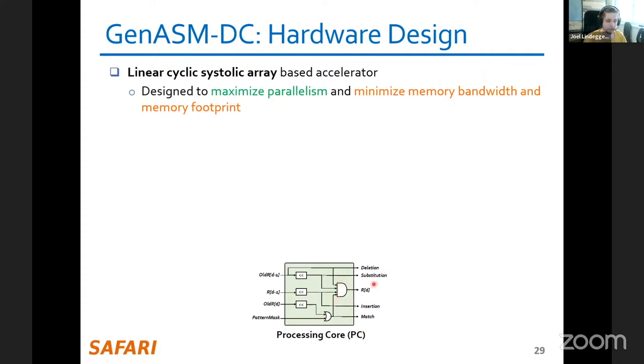This is just a single instance of this, and all of these are 64-bit wires. But it's really efficient in hardware. In fact, these bit shift operations, in hardware, are not even operations. A single bit shift in hardware just means you move some wires over. So you could even ignore this part. And then it's just a 4-input AND gate and a 2-input OR gate. So at the lowest level of hardware, it's really efficient.